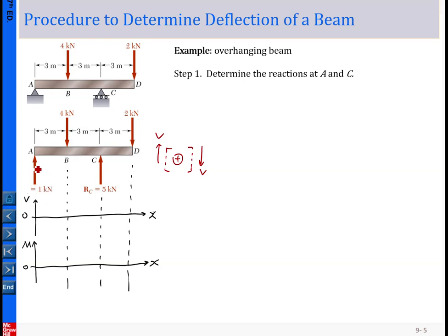Now we determine this one. Here this one is positive, starting from 1 kilonewton, and then constant, and to here we have 4, so downward by 4, so this is -3, and constant, and now upward by 5, so here from -3 up to 2. Then keep constant to here. Now the moment at the free end, so this is called the free end, so both ends are free ends. At the free end, the moment equals 0. Keep this in mind. So we start from here and end up at 0 here.